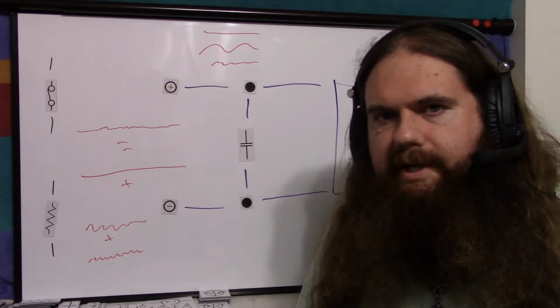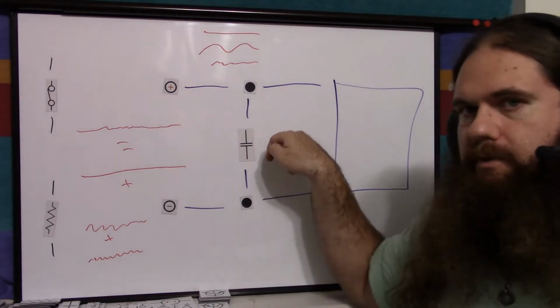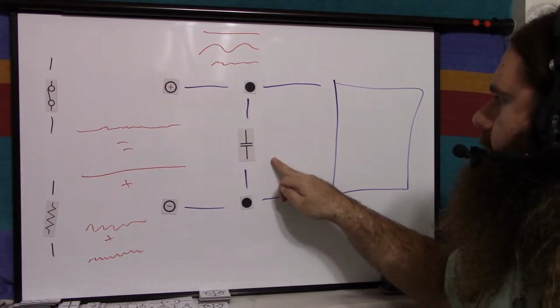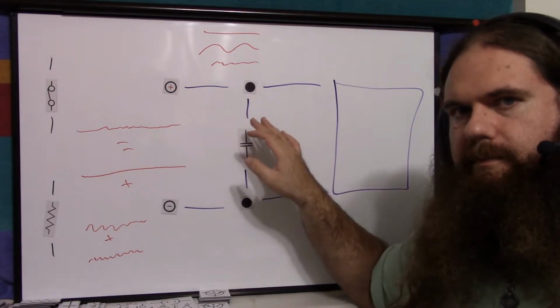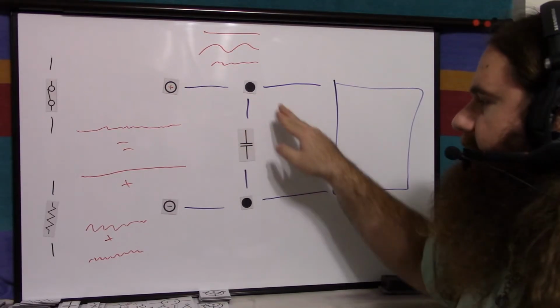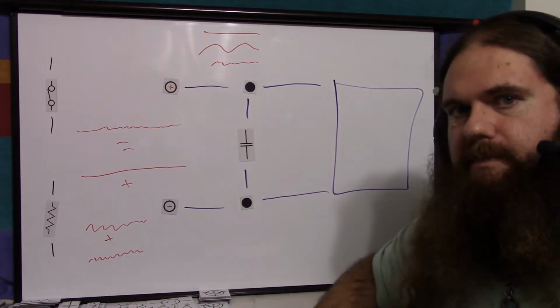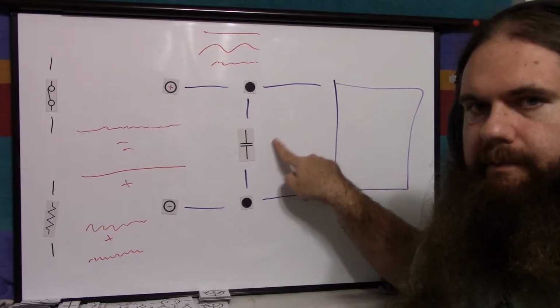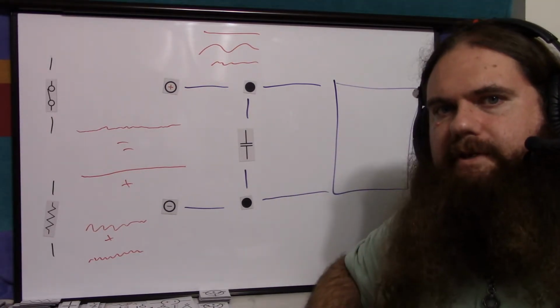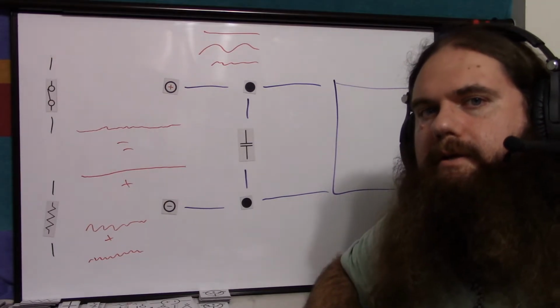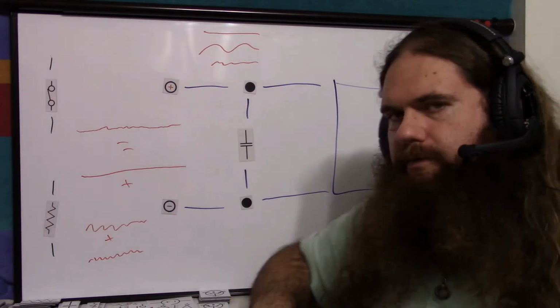And that's not how we conceptually see it. Conceptually, when someone explains a bypass capacitor, they say, well, normally this just holds a charge from the power supply, and anytime the power supply dips, this will make sure it gets its power by supplying it, by being like a battery. And yes, that's also true. Sometimes you'll find there's 7 different ways to explain the same thing, and they're all correct. There's a lot of overlap in life.